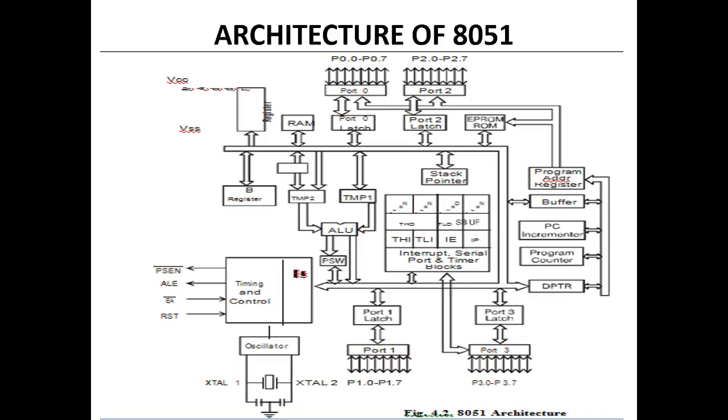At the beginning of an external memory cycle, the lower order 8 bits of the address bus are output on P0, that means port 0. The same pins transfer the data byte at a later stage of the instruction execution. These port lines can be operated in different modes, and all the pins can be made to do many different tasks apart from the regular IO pin functions.